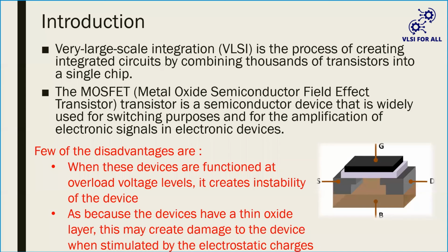Team, remember, in general, whenever the input is dynamic, I'm talking about dynamic input, 0 to 1 or 1 to 0, at a particular point, maybe in a fraction of microseconds, both PMOS and NMOS transistors become on.